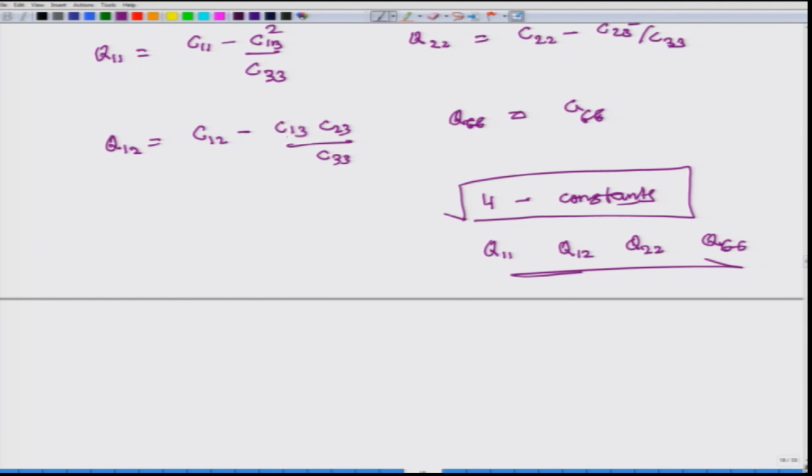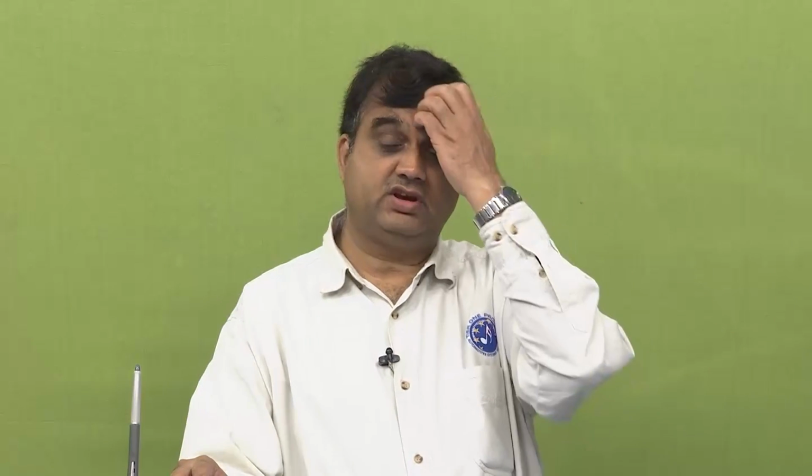Okay. So, this is the conclusion of our discussion for today. What we have discussed today are several types of materials. We showed that starting from an especially orthotropic material which has 9 constants, a transversely isotropic material has only 5 independent elastic constants. If the material is isotropic in nature, then there are only 2 independent elastic constants.